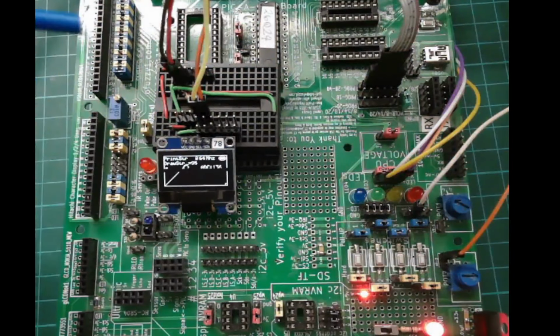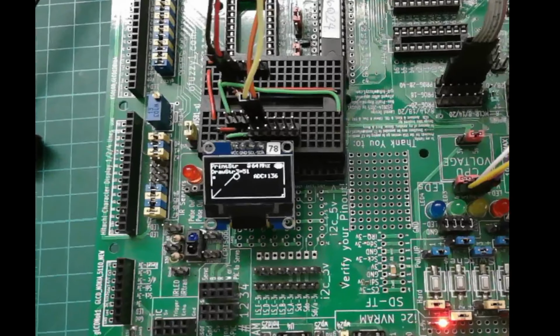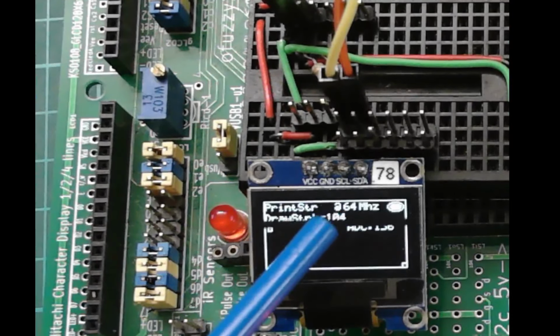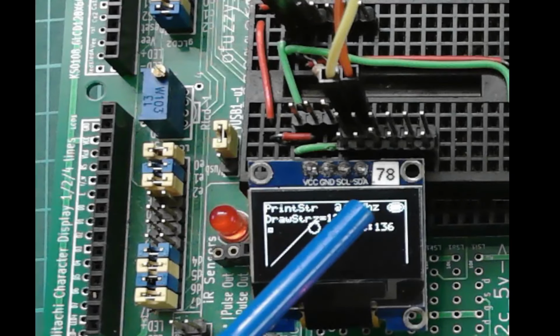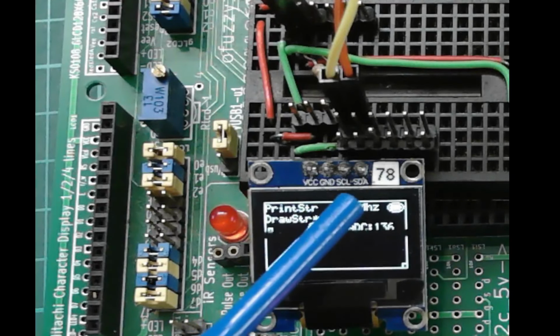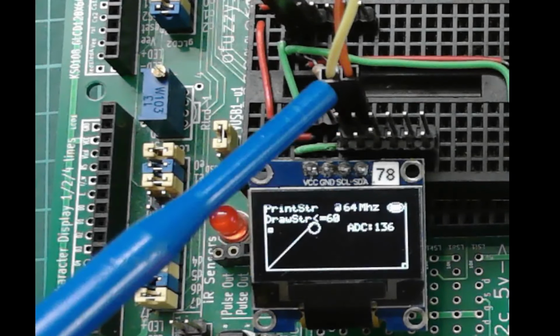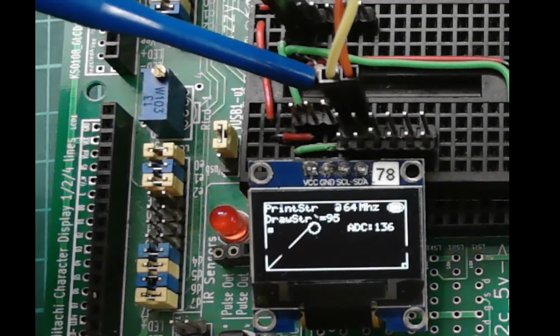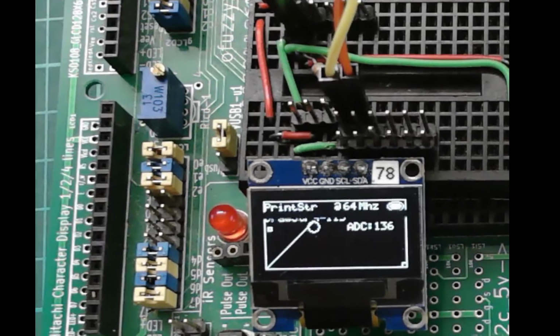Let's have a look in here. For those, let me just zoom in. I think I can zoom in with my camera. If I zoom in here, not only do I know it's on address 78 because it's written on it, you can see SDA here on the right hand side, and then to its left the SCL, and I've got those connected. And if you look just over, you can just about make them out. There are 2 resistors pulling it up, and I'll show you that circuit in a moment.